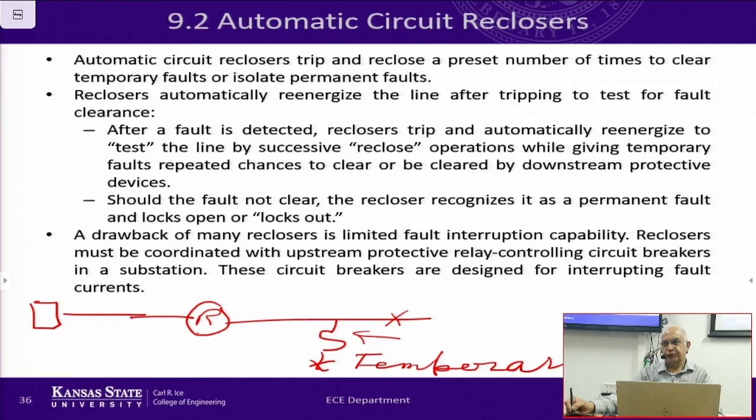So you have to choose the recloser characteristics, which is the faster part of the operation, in such a way that it trips before the fuse operates.